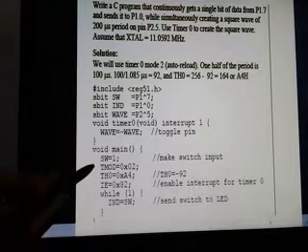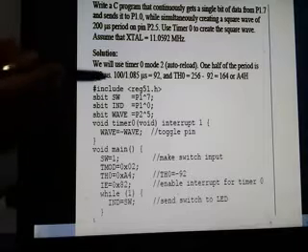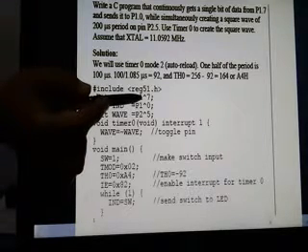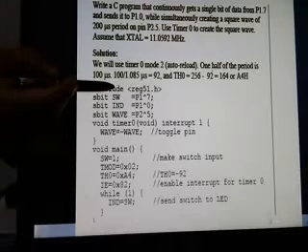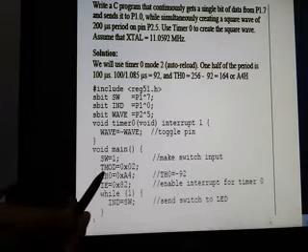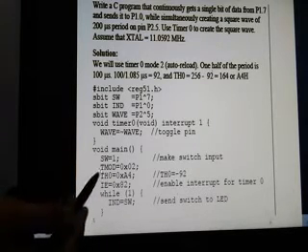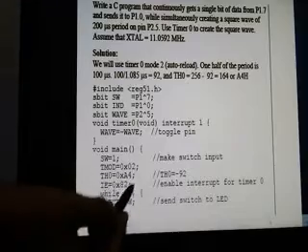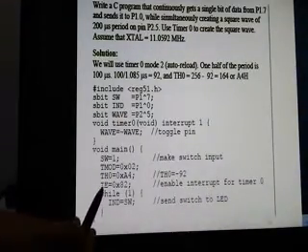And what is to be done in the main program? In the main program, first take the value from P1.7. P1.7 is given the name SW. So define P1.7 as input by giving SW equal to 1. Configure TMOD as 0x02, timer 0 mode 2. Okay, TH0 count we have already calculated A4. IE has to be configured here.